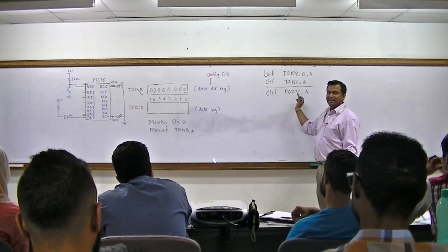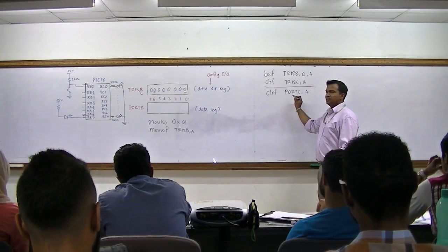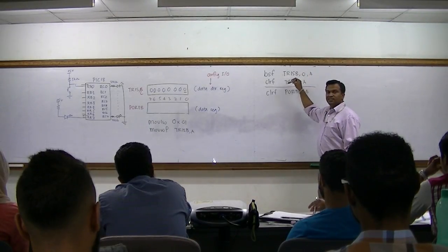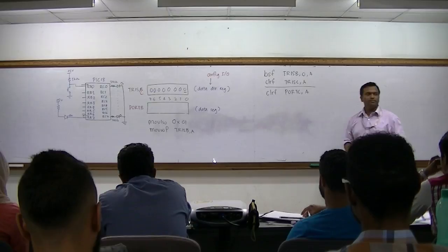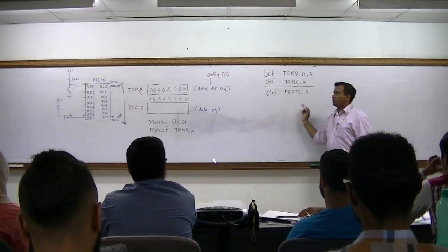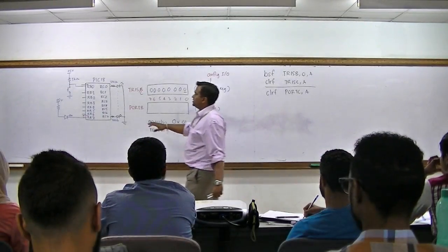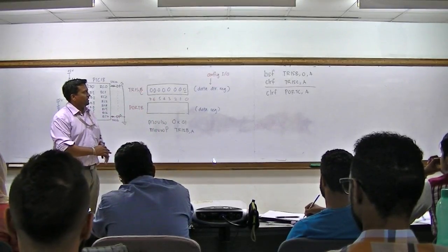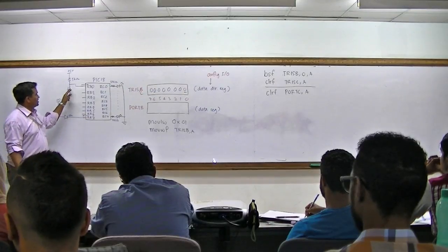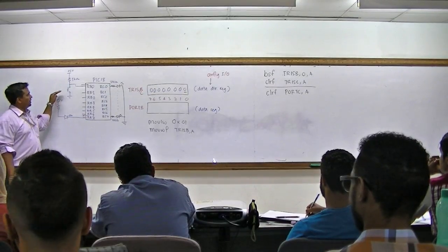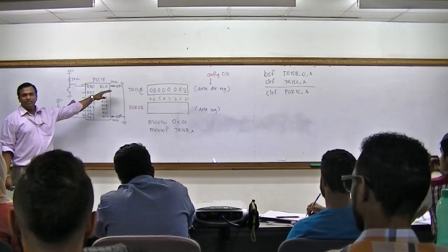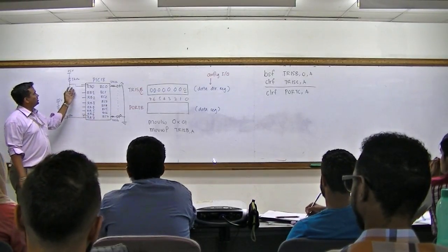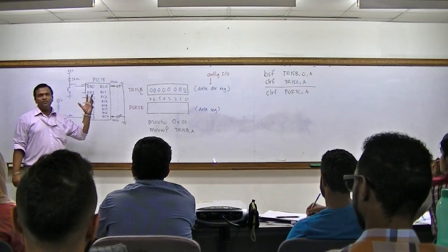Therefore, all the writing and also reading should be done at the data register. Configuration is done at the TRIS register. Is it clear? So when you do this, clear at port C, initially all the LEDs will be off. The next thing is, we have a switch here, right? Let's say when we press the switch, we want all the LEDs to be on. So how can we actually check whether the switch is being pressed or not?